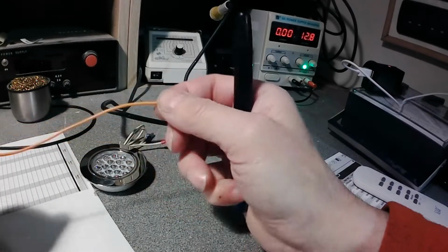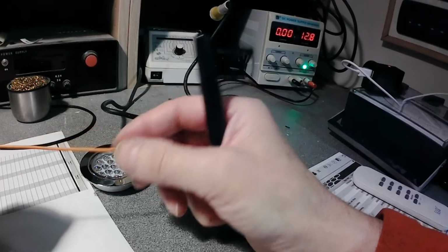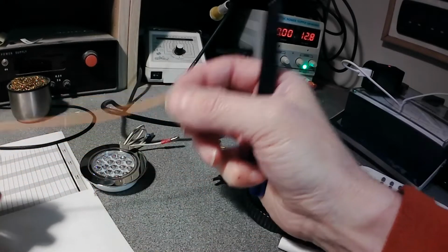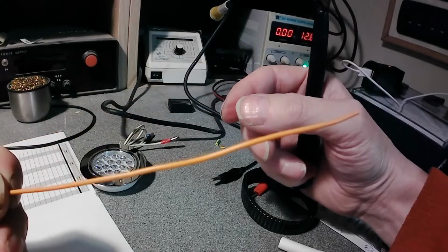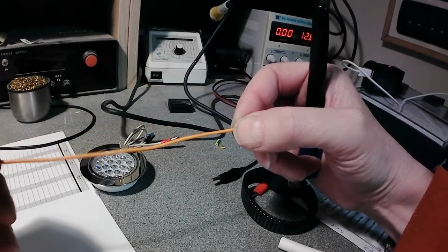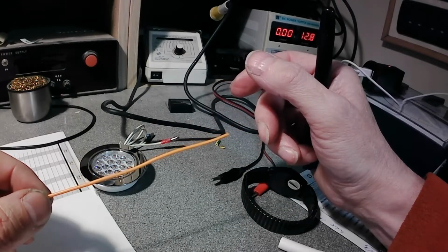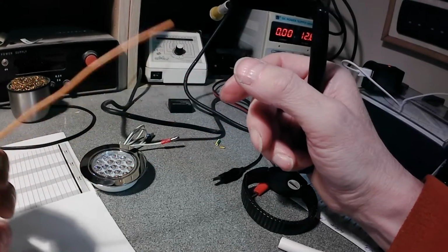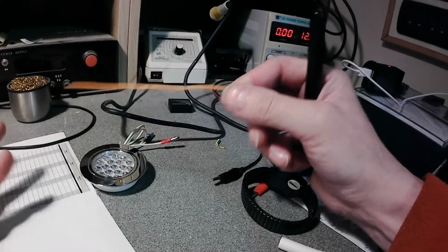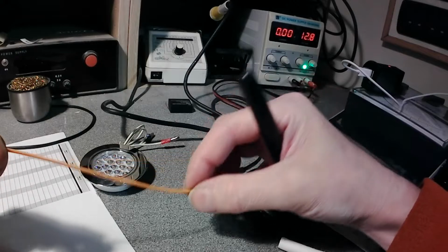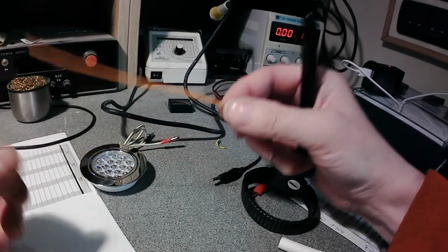You can find calculators on the internet to calculate the voltage drop. If we take such a thin wire and send 16.5 amps through it, and let's say this wire is 7 meters long, like in a van where we sometimes have such long wires, the voltage drop on this wire will be 4 volts.